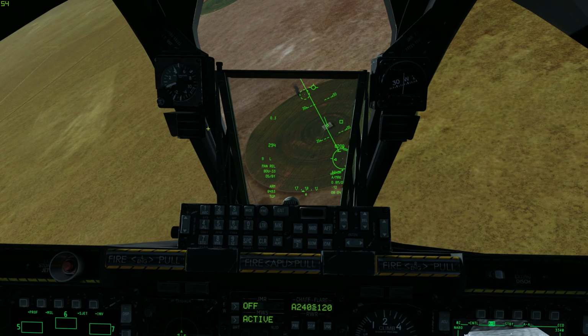Track altitude is 3.6, which is 3,600 feet AGL or 8,495 feet MSL. Track altitude is the altitude at which the desired dive angle should be achieved, with the target under the pipper and the pipper tracking up to the target.